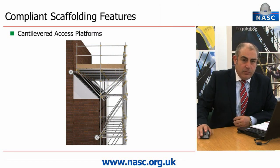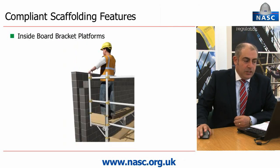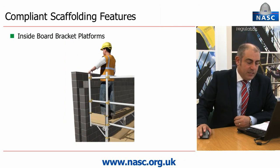Cantilevered access platforms to the inside face of independent scaffolds. The use of inside board brackets, or as they're commonly referred to, hop-up brackets, up to 500mm above or below the working platform.